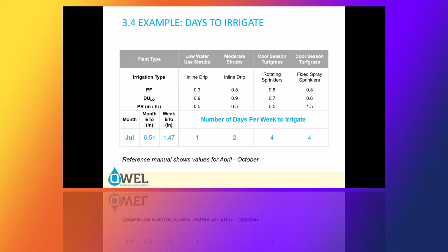In this case, we're assuming that the irrigation controller operates with a weekly schedule, so the minimum irrigation frequency possible is once per week. So again, the minimum irrigation frequency possible is 1 per week. Some controllers don't have this limitation, and you can have a monthly schedule that allows for less frequent irrigation cycles and a deeper application of water. For large established plants and trees, this encourages deeper root establishment and therefore a healthier plant or tree.